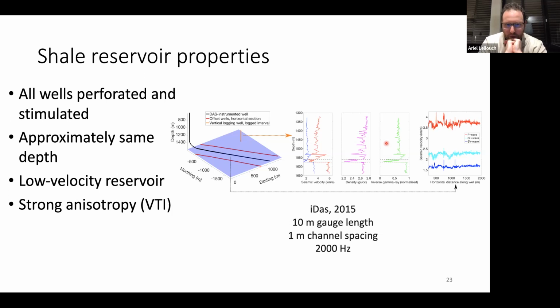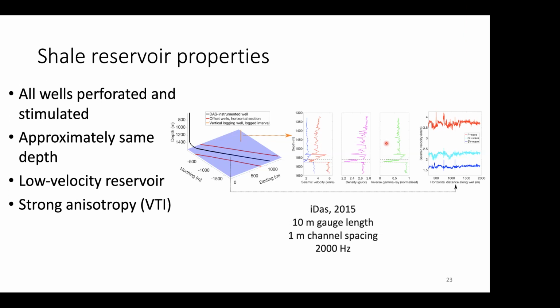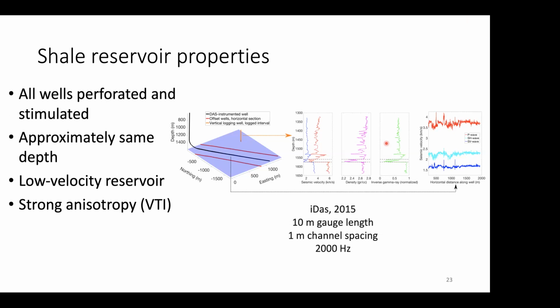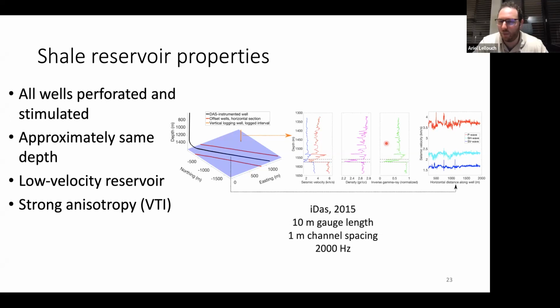Yeah, the problem with the waves that I'm looking at, which is mostly the crosswell data, is that we're seeing an average of the properties along the entire propagation path. So to separate exactly the conditions near the wellbore, we might have to look at the same well experiment where we had the DAS fiber perforated.